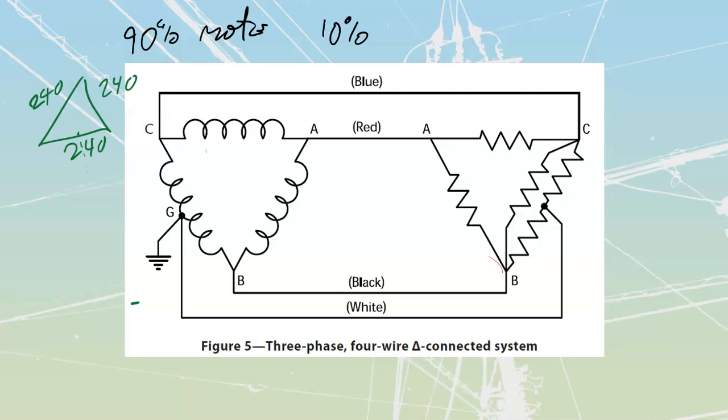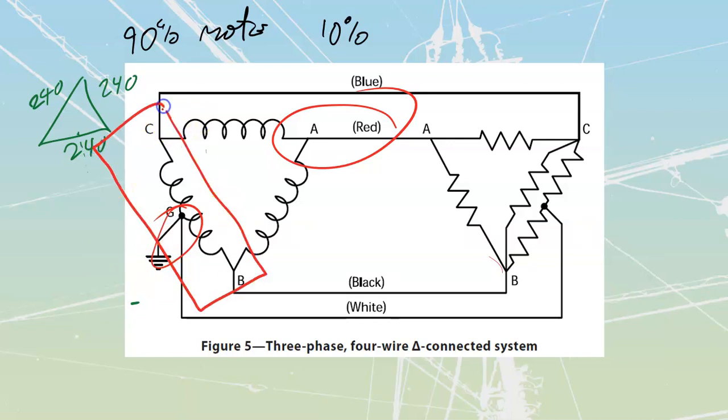Now you got a bunch of special rules as well. The code is going to refer to the one leg as being the high leg. The A leg over here is going to be the high. The grounded conductor, this conductor over here, this neutral, they call it a grounded conductor, has to be in a compartment provided for single phase. So you're going to have to have a single phase panel that's basically going to incorporate all of those sections over there. And the A phase has to be in a completely different section of the panel.